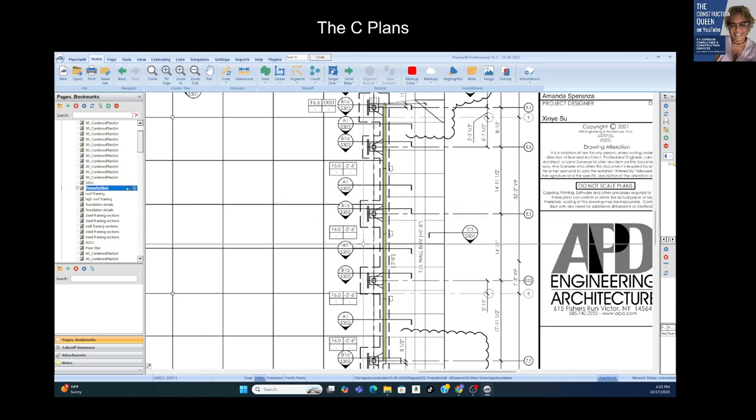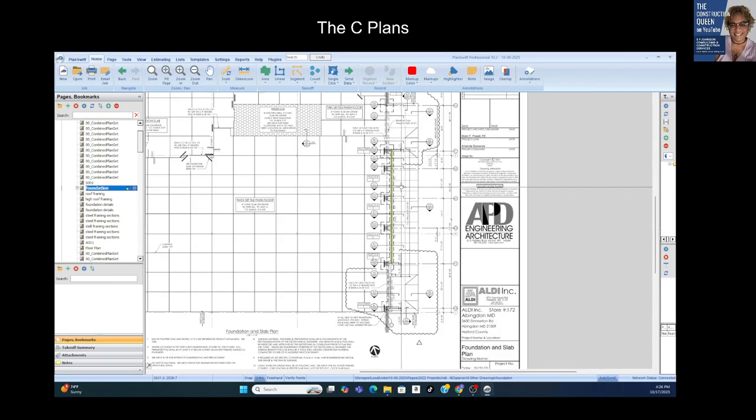So, and you see A1302, A1302, A1302. I could just measure all one, just keep measuring. I don't have to break that up because it's the same. And it's basically the framing in between all of the column pads. So I'm just going to go all the way down and then incorporate each of the column pads individually or anything else that's different.